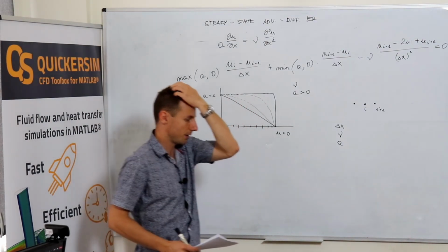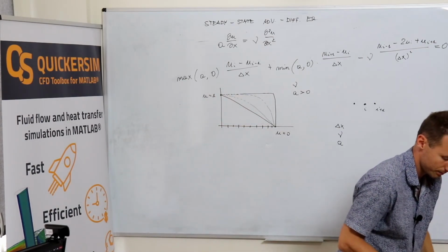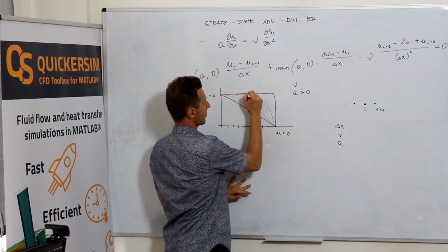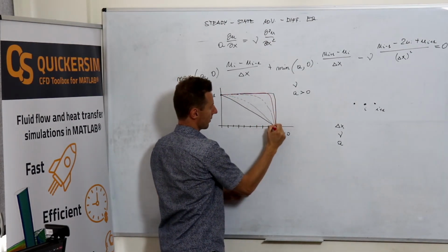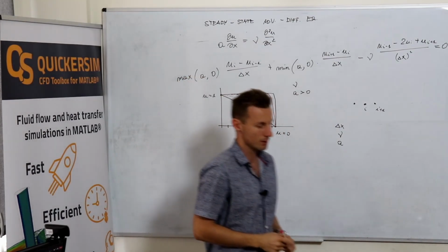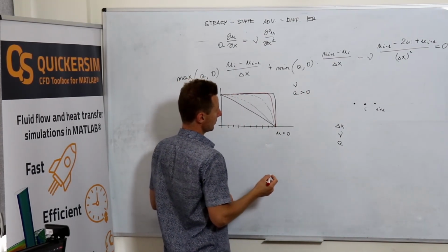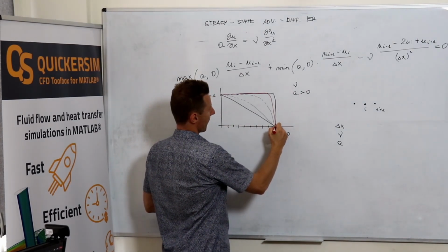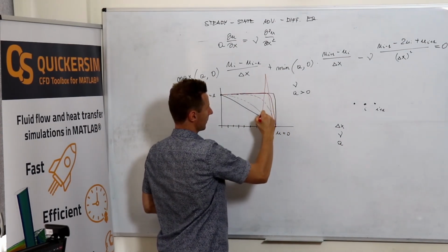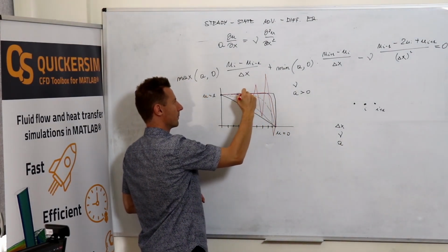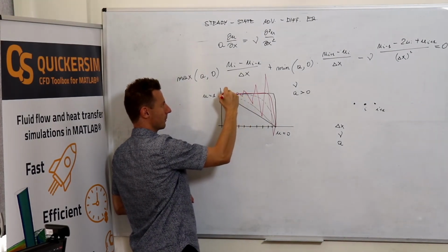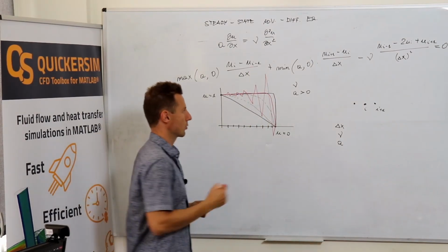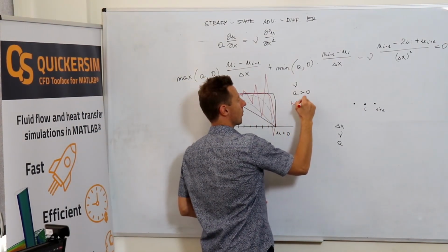If you go higher with the velocity, you know that the analytical solution is probably something like that, but your numerical solution will do something different, and you can quickly get something like this, more or less. You get huge oscillations, huge wiggles, that's how people call them.